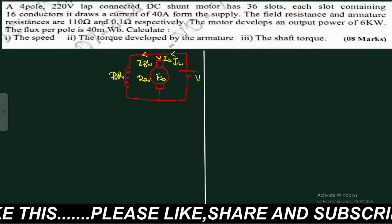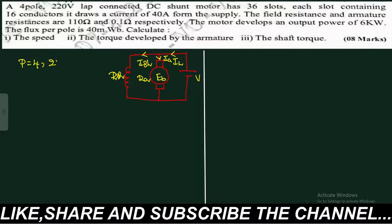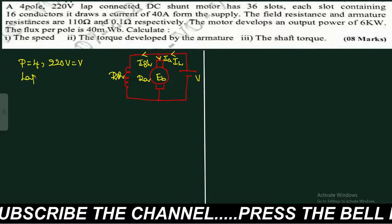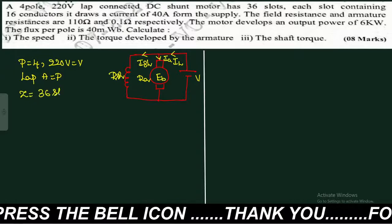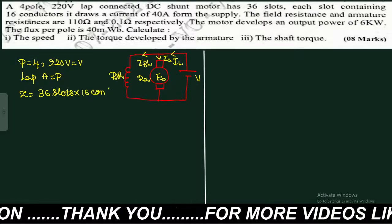A 4 pole means the number of poles P is equal to 4. Next, 220 volts is the terminal voltage, that is the supplied voltage. Lap connected means A is equal to P. It has 36 slots, and each slot consists of 16 conductors per slot.